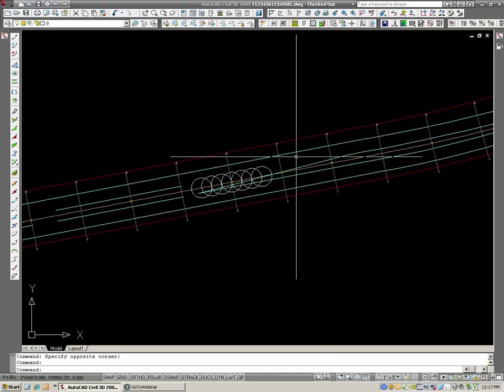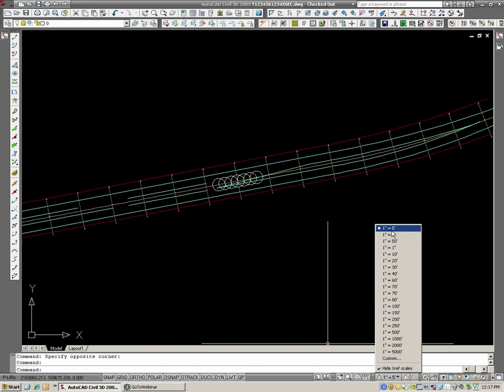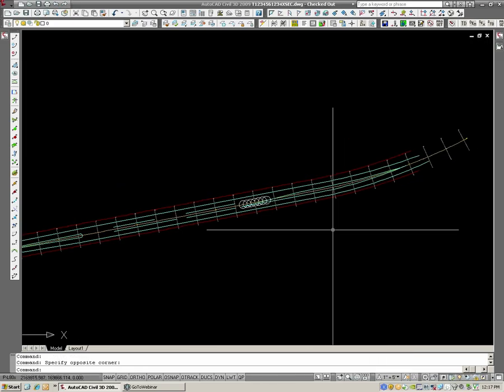What that will do is that's going to change your drawing to 5 scale, and it's going to automatically create a nice 5 scale annotative style down there for you. So you sort of kill 2 birds with 1 stone. It's much quicker, much cleaner, and you get a nice scale that's built the same way as the rest of them. So we want to set that drawing to 5 scale.